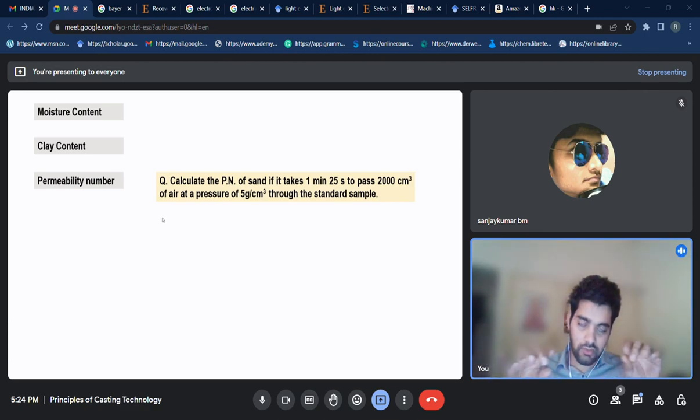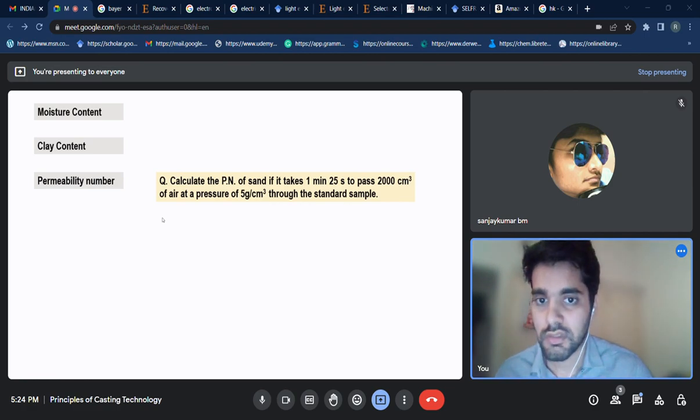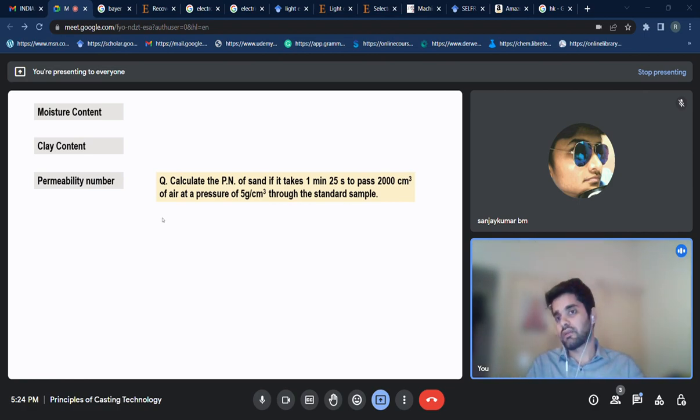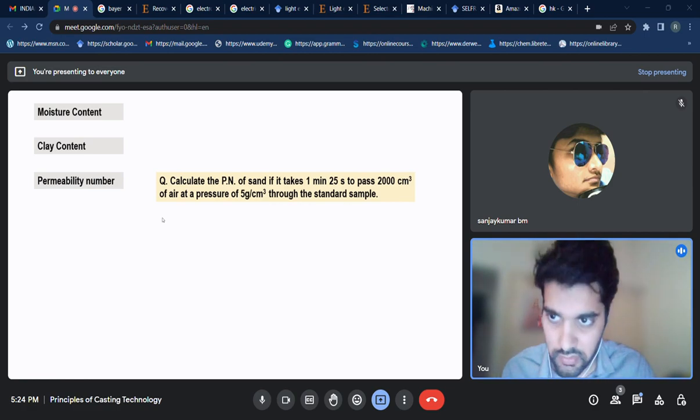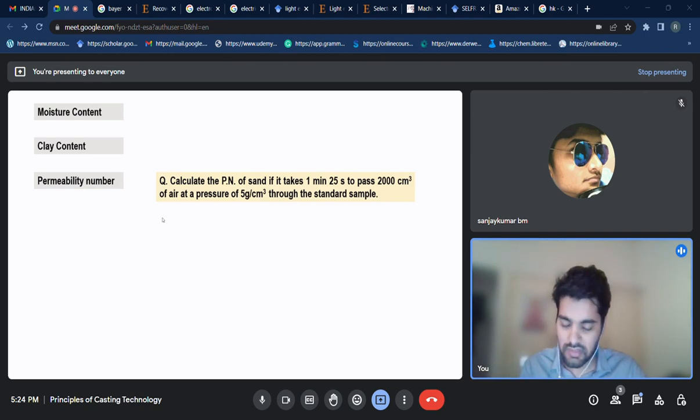So what people do in landfills is use something called a liner. People design a liner so that anything which percolates comes first in contact with the liner, and only after the liner has aged, like 10, 20, or 25 years, does it fail.